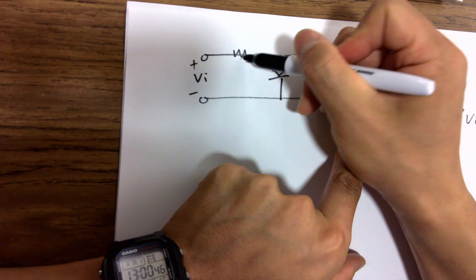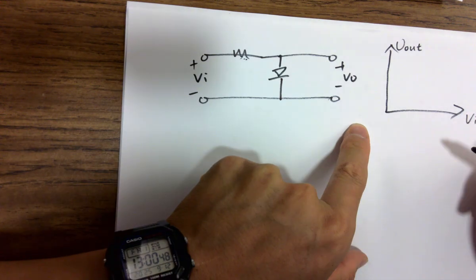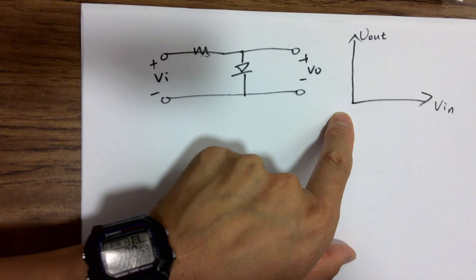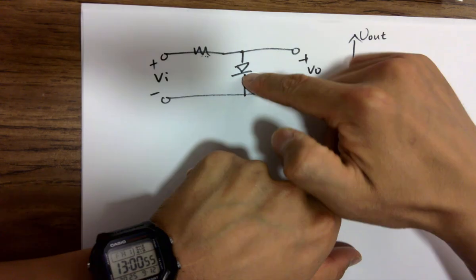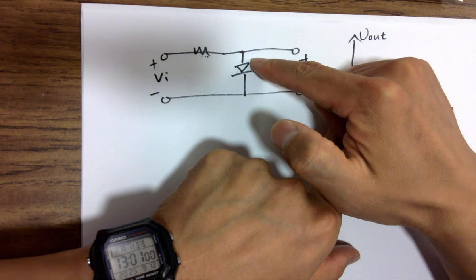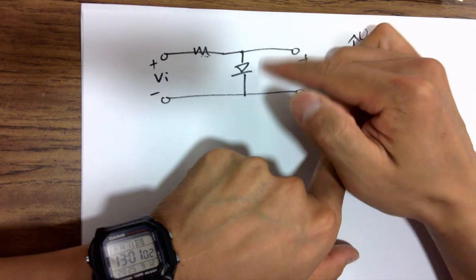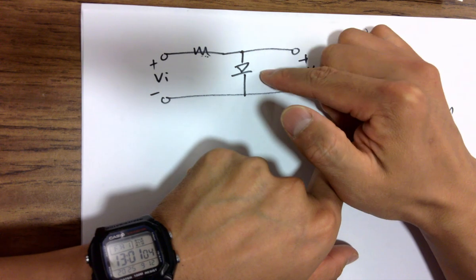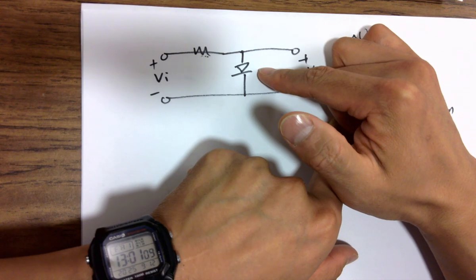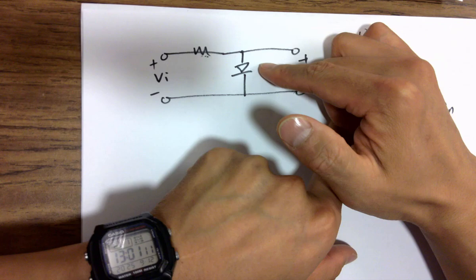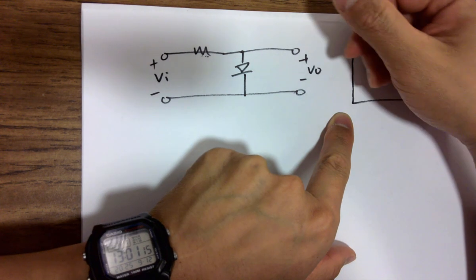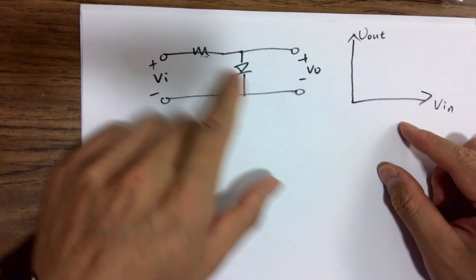Why do I need a resistor here? All diodes require a resistor to protect them. It's limiting the current, because diodes don't have large internal resistance. If you directly short it to the power supply, you can blow it up really quickly, including LED lights. It will reduce the lifespan by 10 times or so, or even more. So all diodes require a protection resistor. It could be several hundred ohms, could be 1K, which is fine. It's just limiting the current.